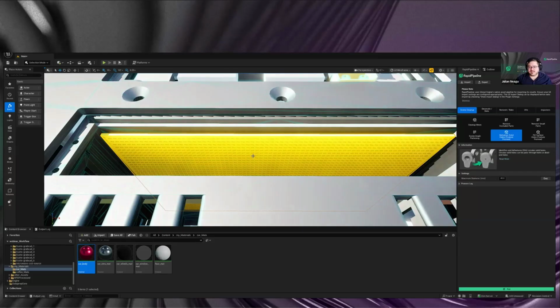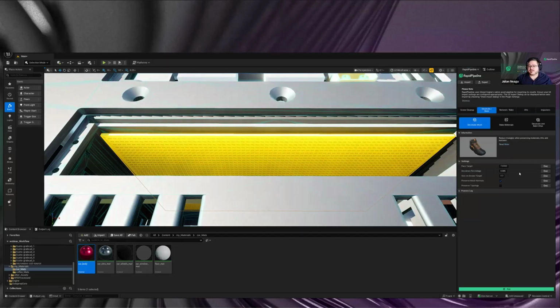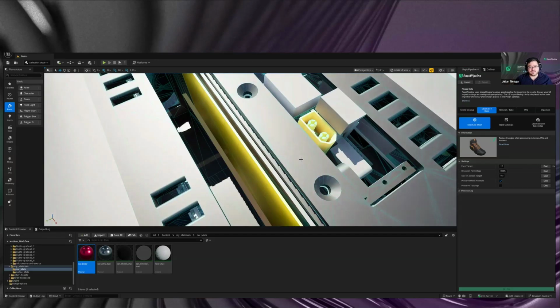The cool thing is once the holes are removed, we can do something like a decimation. We could say, for example, this is basically a cube, so we go with 12 triangles, so six quads, and run this on top of the hole closing. If you would do this on the model with the holes, we might get into problems with the decimation because of the holes. Now that we have the holes closed, we have perfectly perpendicular surfaces in a really good orientation, also for the normals.